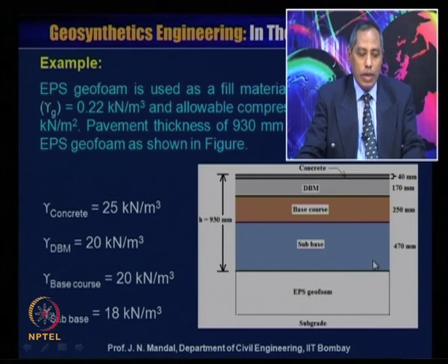The sub base is 470 millimeter, the base course thickness is 250 millimeter, the DBM is 170 millimeter, and the concrete is 40 millimeter in thickness.